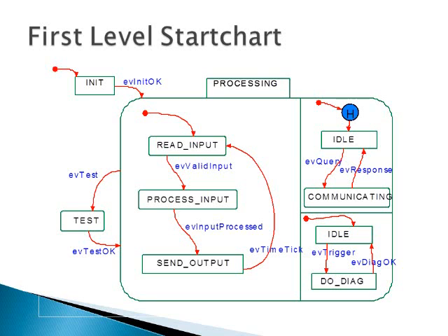So as I told, we can do away with the communication. So once we debug communication physically, and once we have that configuration data constant, then if we check all the inputs to the extent of the resolution of the ADC, then we can claim that we have checked all the software paths for all possible variation in the input space.